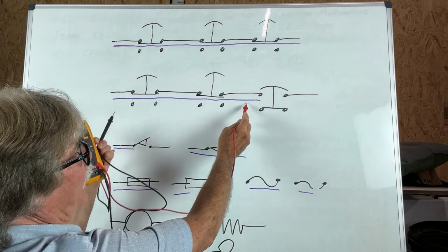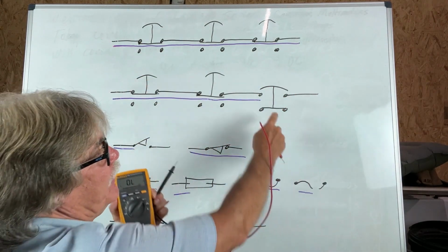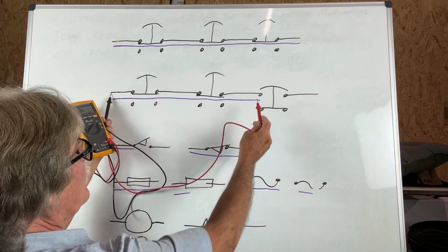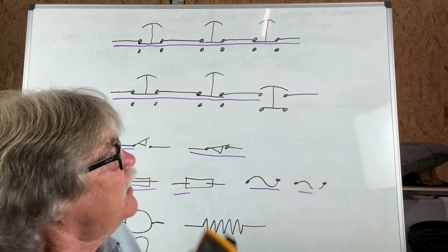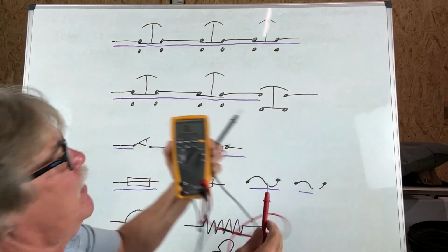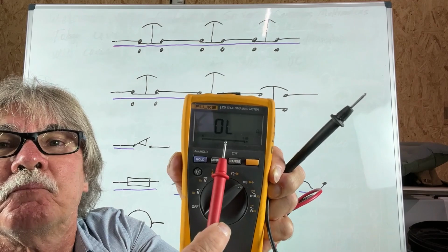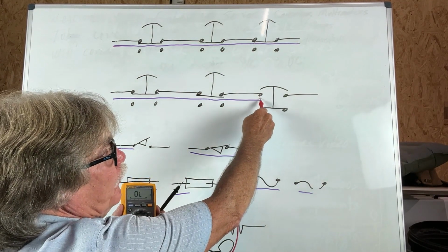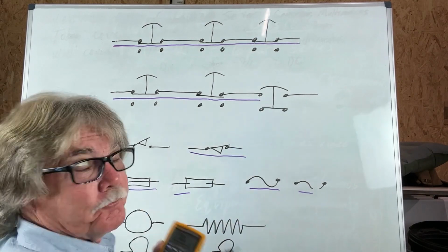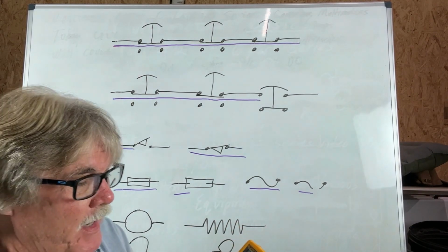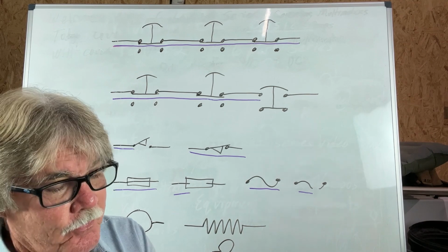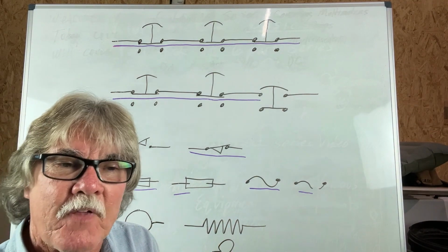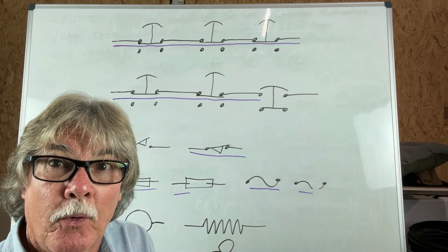Now, if we went down to this one, and somebody depressed one of these e-stops, and it was pushed, then if we measure from here to here, it's going to read 0, but if we measure from here to here, it's going to give you OL, because we have an open and the current flow stops at this point. So that's a good way, using resistance and measuring our ohms or using continuity, of telling us if we have flow or not.